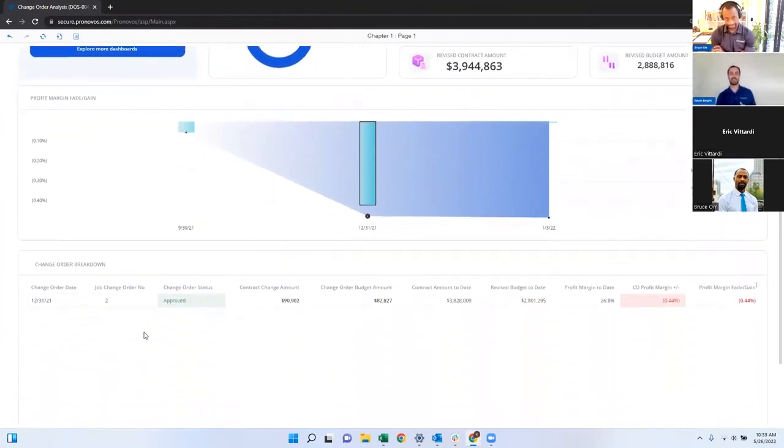Because I think that's something that sometimes gets missed. A lot of subcontractors in particular might bid a job at a 20% margin, but in their subcontract with the general contractor, they might be limited to what they can put on for markup for additional work. Maybe it's only 10 or 15%. And sometimes that is what it is. But understanding how that actually trickles down and impacts the final financials of the project is a really important thing to understand and make sure you're doing.